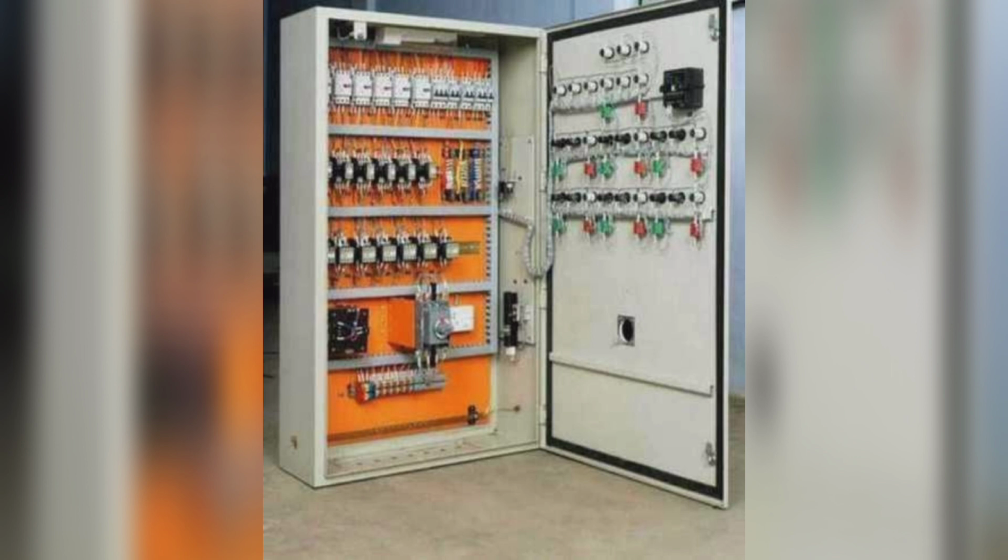Okay, then what is an enclosure? Let's get started. First, let's talk about the enclosure, the metal electrical control box that contains all the electrical devices of the control cabinet. Enclosures are often aluminium or stainless steel, and the size will vary based on the size of the process. An electrical control panel's enclosure can have multiple sections, each with an access door. The size of the enclosure is commonly referred to by the number of doors or enclosure bars.